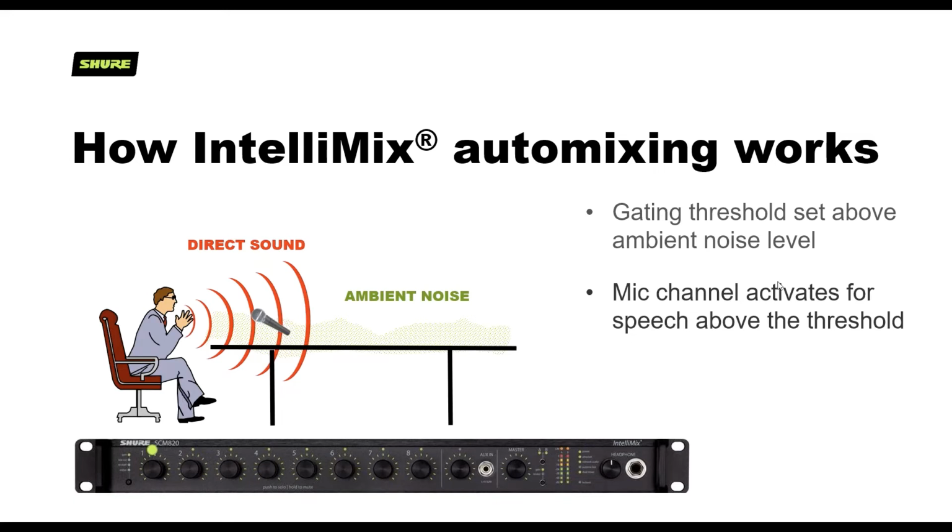The automatic mixer thinks that's noise because it's not very dynamic and starts gating the channel off. But it might go off and then on and then off and then on. It gets confused by program material. So again, automatic mixers aren't a solution for musical applications, but in any speech application, typically, if there's ever going